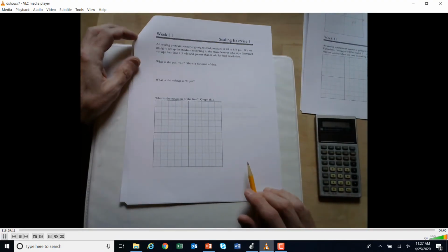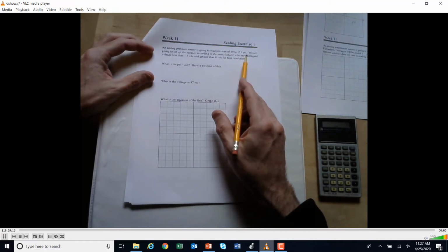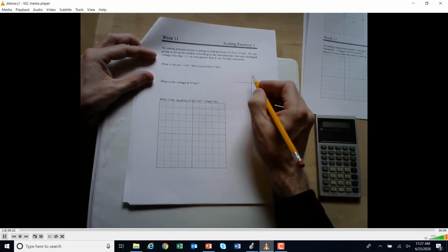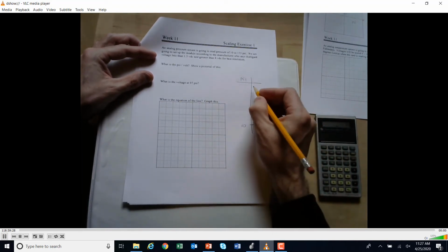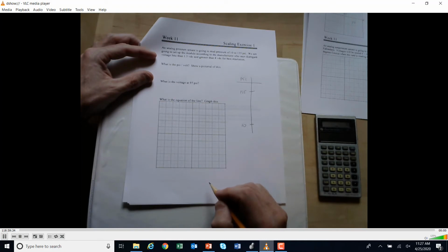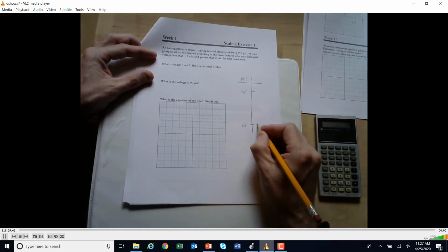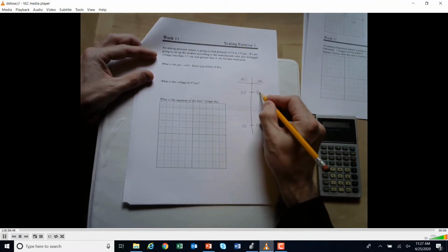So we'll come right here. The first one says an analog pressure sensor is going to read pressure from 10 to 155 psi. What I like to do is draw this on a little scale like this, and I'm going to put psi right here. It's going to read from 10 up to, let's say, 155. So that's my psi. We're going to set up the module according to the manufacturer, who says disregard voltage. So really, we want it to read between 1.5 and 8. That is what we want it to read. So at 1.5 VDC, this is my VDC right here, and this is 8 VDC.